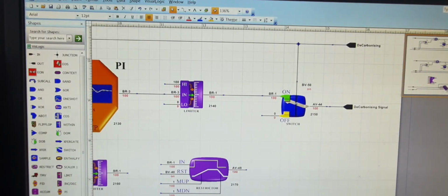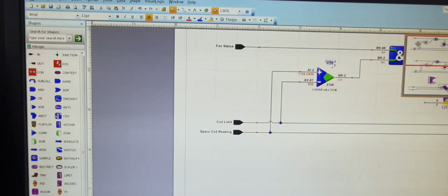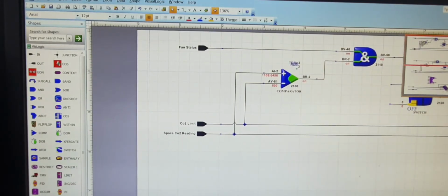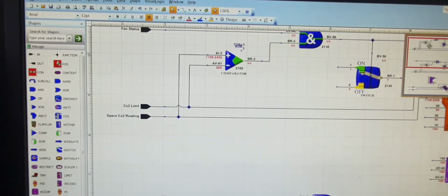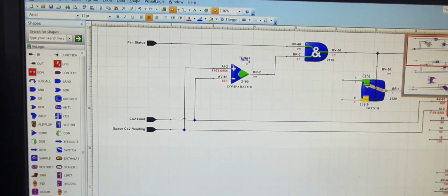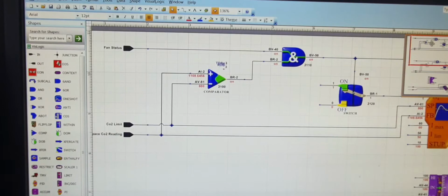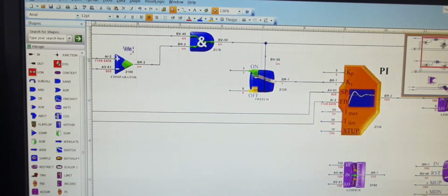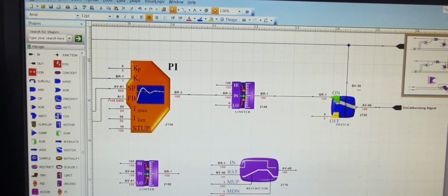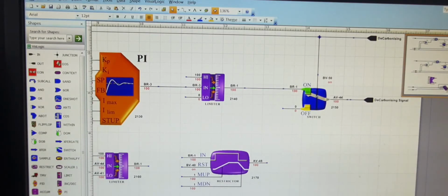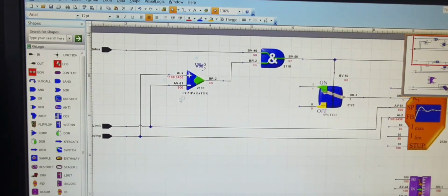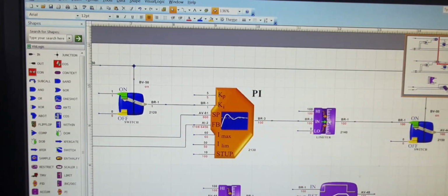Regardless of what the set point is, even if you're feeling cold, this condition, because it's a high priority condition, you don't want CO2 levels high in the space. So even if you're freezing, even if you're calling for heating, it doesn't care because your CO2 levels are high. So it's calling for full ventilation. It opens the VAV box until the ppm level goes back below the set point. So this takes priority. So this should be understood clearly.